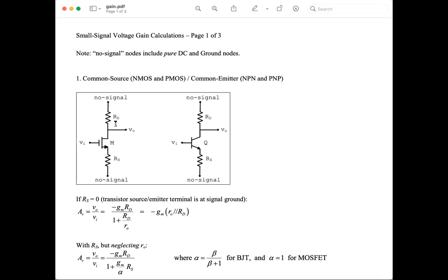In the case of the Cascode, I don't have an RD and I don't have an RL, but I have a next stage, which is a common gate. So this RD here that I will use for the common source gain in this formula, minus gm RO parallel RD, this RD would be the input resistance of Q2, the next stage in the Cascode.